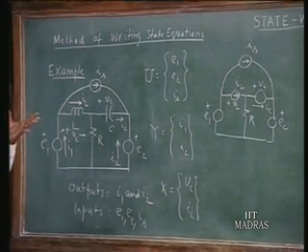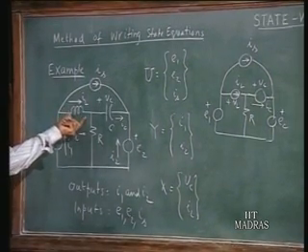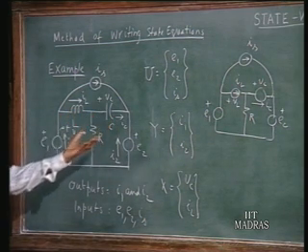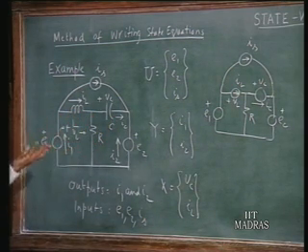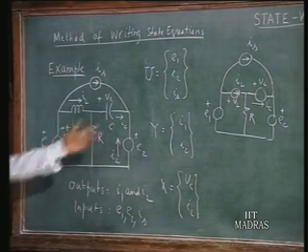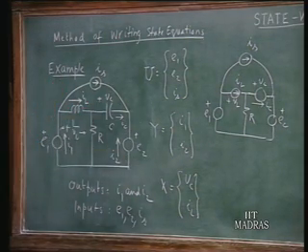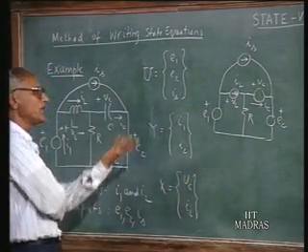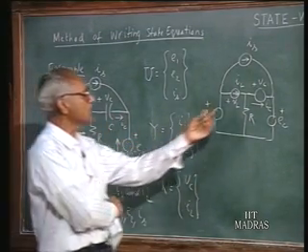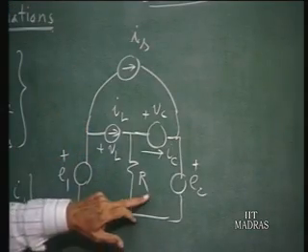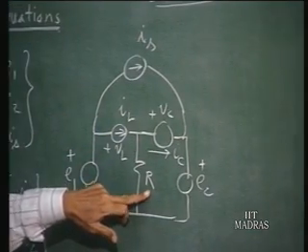It is only a convenient representation, representing an inductor by a current source and a capacitor by a voltage source. You do not have to do it. If you can write down the equations for VL and IC in terms of IL, VC, E1, E2 and Is in any other manner, it is possible. But what we want to emphasize is that we have to express this voltage and this current in terms of various sources and the non-dynamic elements that are involved there, the resistance.